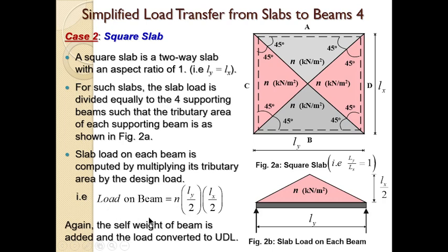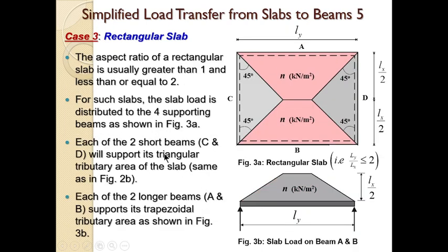Again, you calculate the self-weight of the beam and you add it to that slab load and then divide it by this length Ly. It becomes a uniformly distributed load.